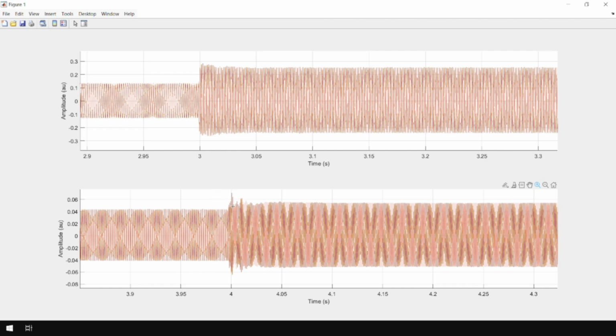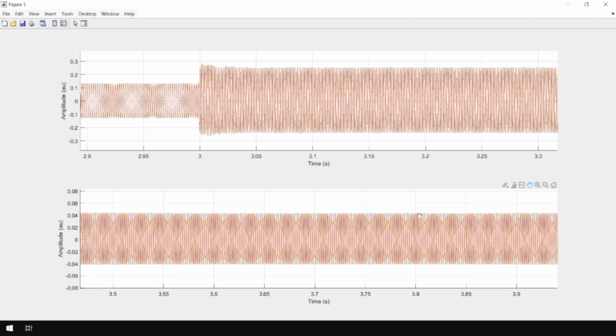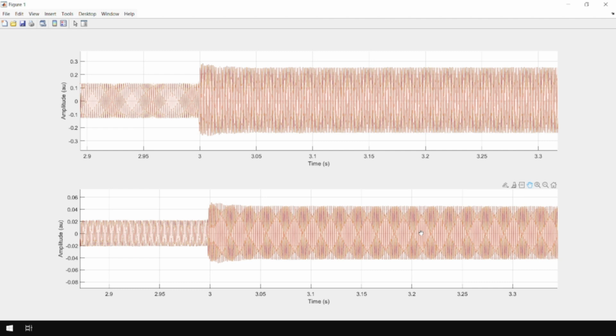Now, some of this will become high frequency noise in the FFT and just kind of go way over there where we don't really care about it. But there's also some low frequency components here, which is actually lower than the measured frequency. So that might be screwing up the previous measurements over there. I need to do some time domain filtering of this data to pre-process it and get rid of any weirdness that might be affecting us there. But you can see the time steps are actually long enough that it does go to steady state.